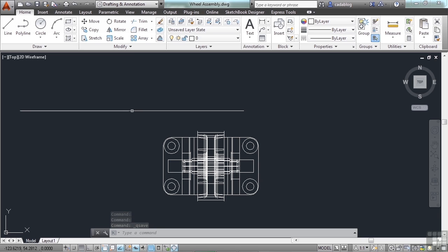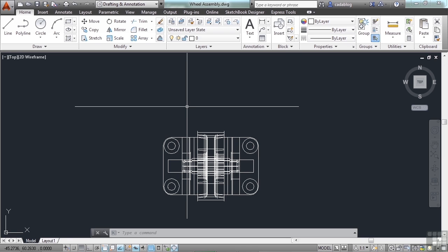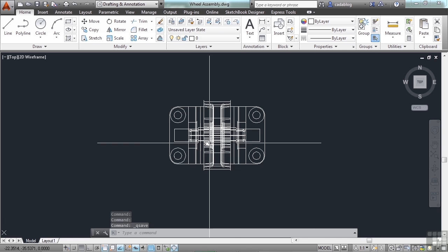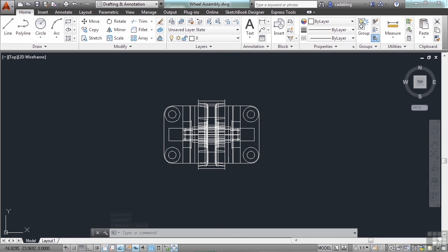While I'm working, I'm drawing lines, circles, trims, edits, copies, paste, whatever. Control S. More lines, some dimensions, I'm moving, I'm zooming, I'm panning, Control S. I've gotten myself into the habit of using Control and S on the keyboard very regularly. It has saved me time and time again because AutoCAD will crash. You will lose your work.